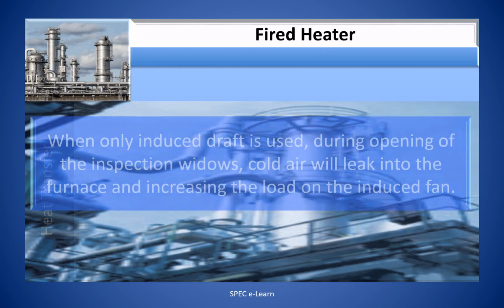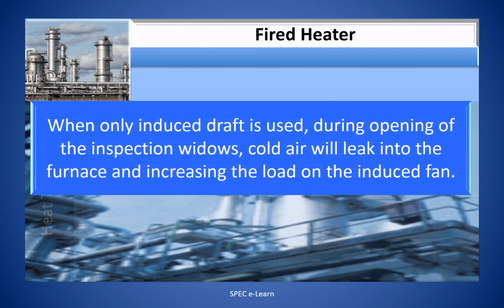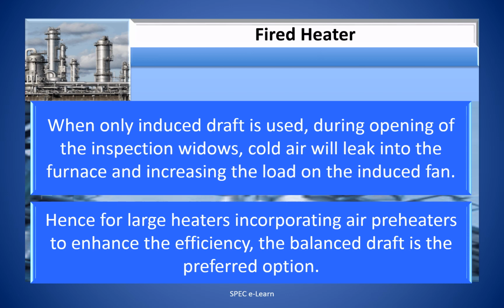When only induced draft is used, during opening of the inspection windows, cold air will leak into the furnace, increasing the load on the induced fan. Hence, for large heaters incorporating air preheaters to enhance efficiency, the balanced draft is the preferred option.